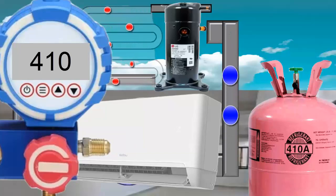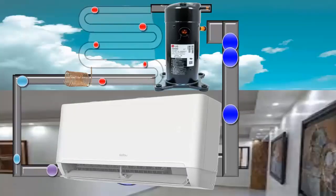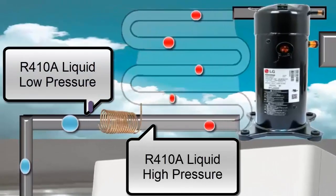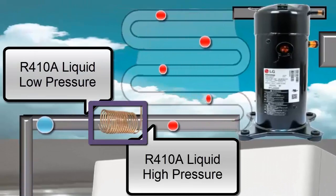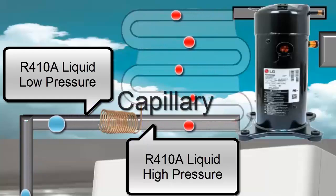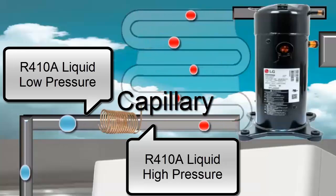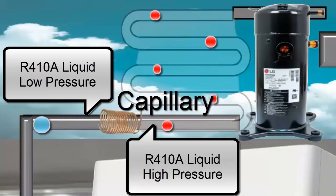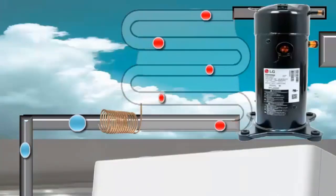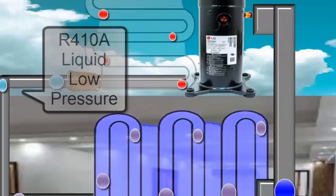Before returning to the premises to restart the cycle, the R410A must pass through the capillary tube. The capillary tube reduces the pressure of the R410A and, therefore, simultaneously reduces the temperature value back to 5 degrees Celsius. The R410A, at low pressure and temperature, returns to the evaporator unit to start a new cycle of heat absorption.